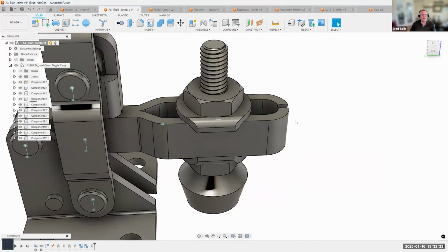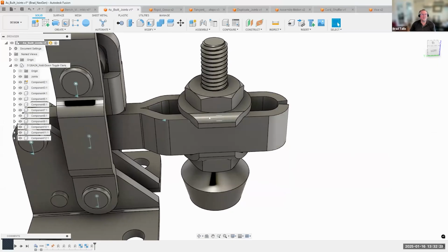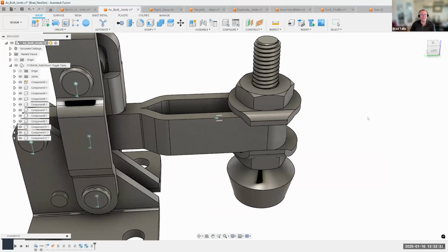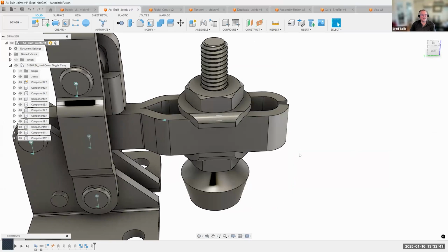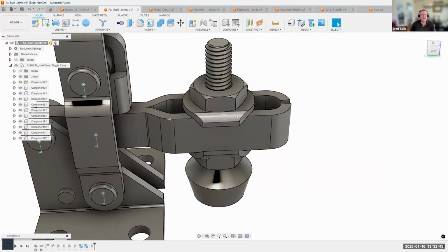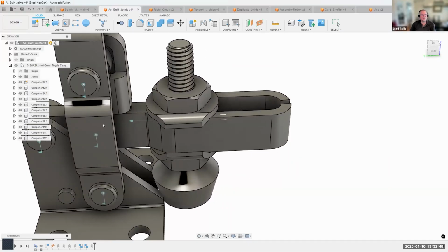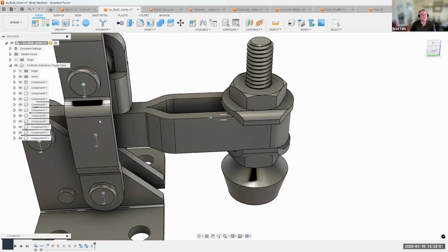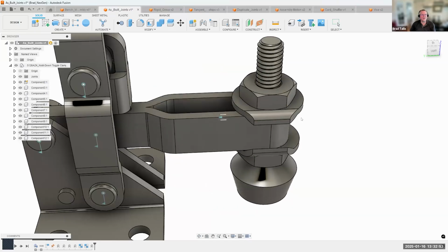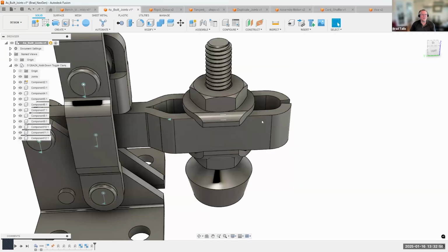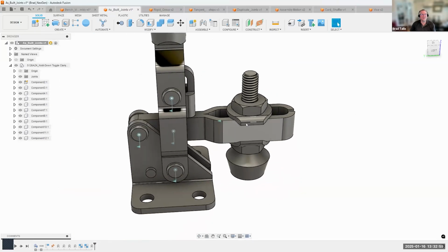What I just basically did was tell it what the minimum and maximum movement this slider joint can do. So if I grab this, you can see even though I'm continuing to move my cursor to the right, it can't go any further than that. And if I let go, it's going to go back to that rest position. And if I drag to the left, it can't go any further because that was the minimum. You can see that's as far as it can go. And if I let go, it's always going to return to that resting position.